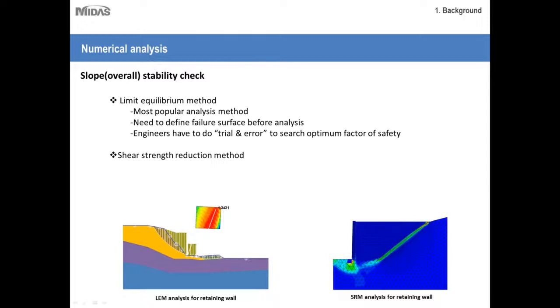And as it proceeds with lowering the shear strength value, it hits a point where the entire slope is mobilized, and at that point it clearly shows that the maximum deformation would occur at this particular layer at this particular force, and therefore you can easily assess when the failure will occur and what the failure plane will be.